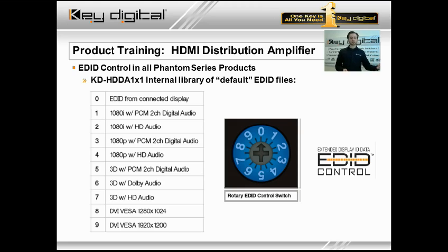Additionally, this is commonly inserted in any application where you have a computer with HDMI output going in to feed a system here, maybe a switching or distribution system or a matrix system, because computers generally are a little slower to respond to handshake negotiation, so you want to leave a nice constant EDID file there, EDID read for the source, in this case the laptop or the desktop PC, to receive.